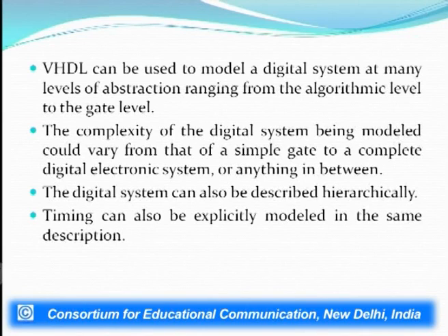Now, VHDL can also be used to model a digital system at any level of abstraction, ranging from the algorithmic level to the gate level. Below gate level, VHDL does not work, that is, the transistor level description of the circuit cannot be made using VHDL. We can only begin from the gate level, and from the gate level beyond, the complete algorithmic, entire system level can be easily designed using VHDL.